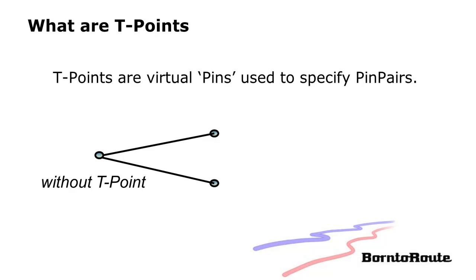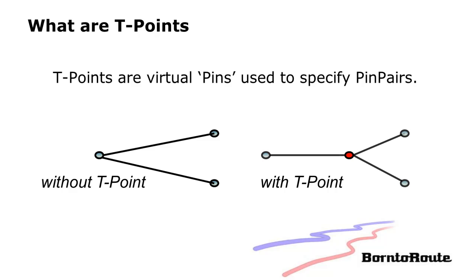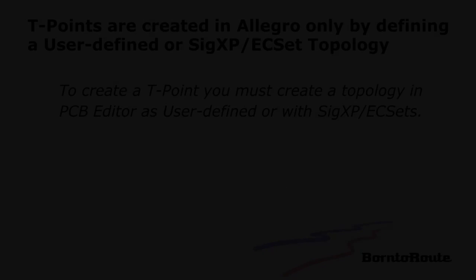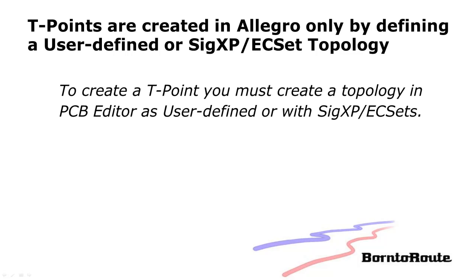So what's a T-point and why do we care? Well, T-points are virtual pins, is a way to think of them, that are used to specify pin pairs. T-points can only be defined as part of the process of defining a larger topology in PCB Editor. You cannot define a T-point in the Capture Desktop outside of a topology.